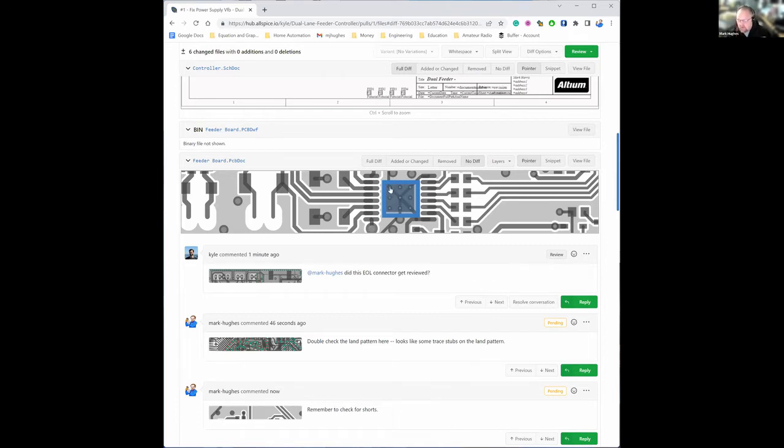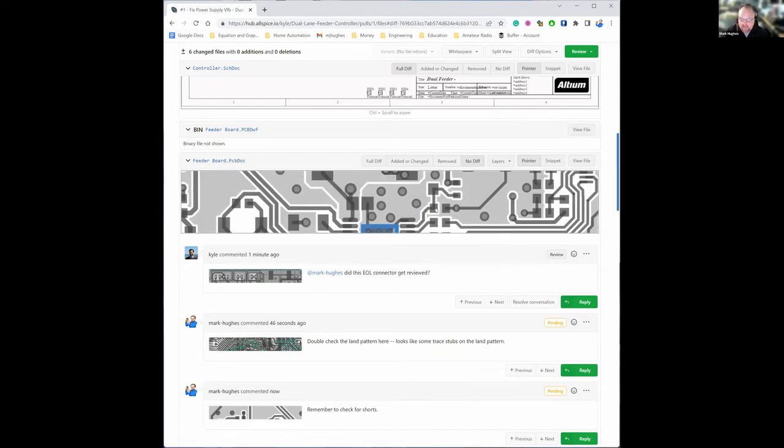However, the best way to do that is really expensive: you cap and fill those via holes, so the solder can't go in, but that is ridiculously expensive. The next best thing you can do is shove some LPI solder resist mask in there. Just cram it full. That works, but again, it's an additional process, so it's expensive. Well, IPC 7351 provides some patterns that you can put on those land pads. Basically, you create solder dams around the holes so the solder can't get in. LPI is free. It's going to be on your board anyway. So that's usually the recommended option that we give people because it doesn't add any expense to the board and it solves the problem.